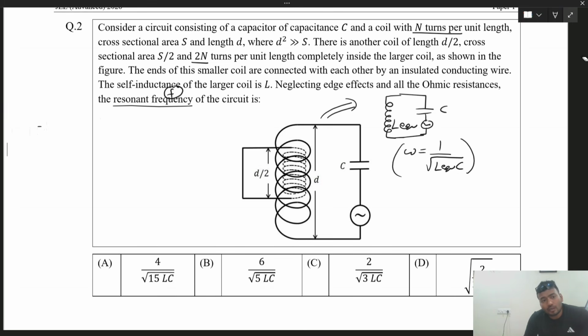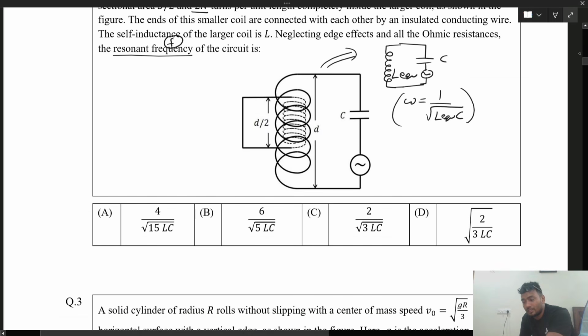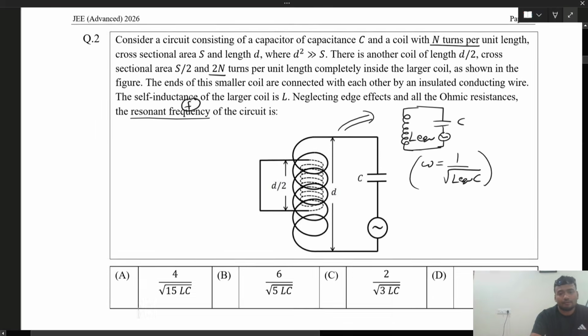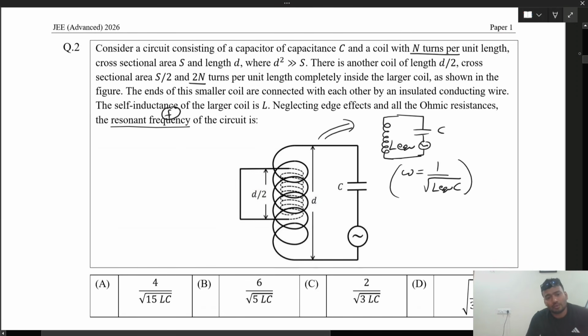These two are basically, instead of that series or parallel combination of inductor, it is more like a transformer, right, with primary and secondary coil. So ऐसे case में how to find out this L equivalent, there is no direct method beta. That's why I say this is a quite interesting problem. So you do one thing first, let us find out the self inductance and mutual inductance of both of the coils. So L का जो formula होता है mu naught n square A by L.